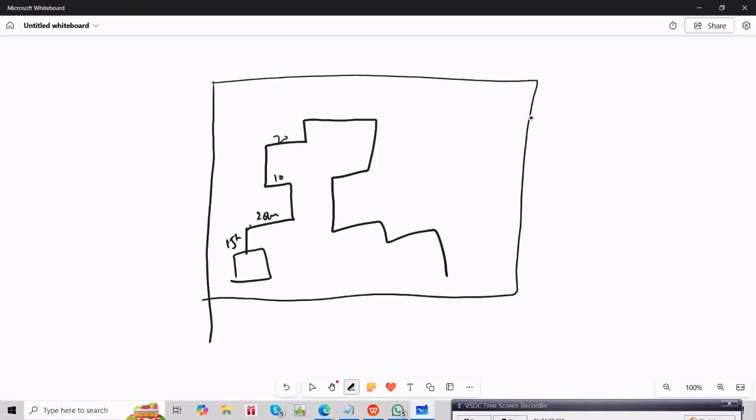So that's why they create GAD. On that GAD, you will mention each and everything: the pipe name, the size, the support location, the sleeper location, and so on. It is easier for the fabrication.